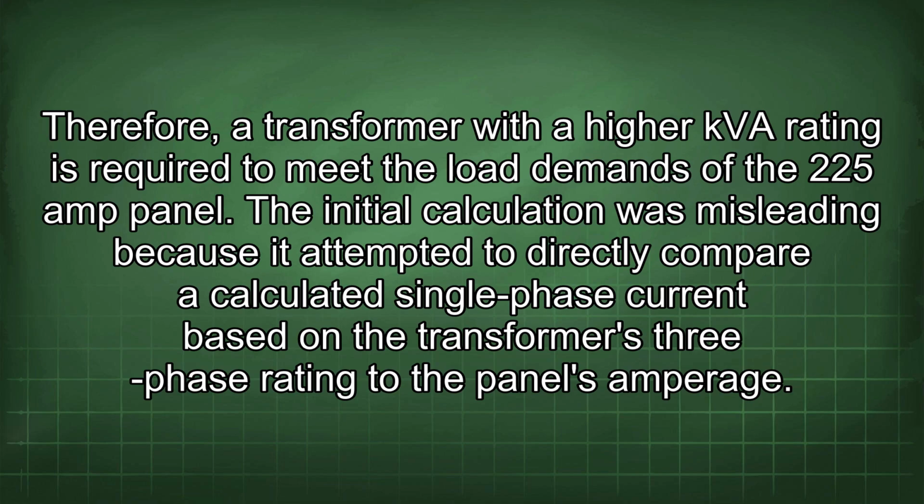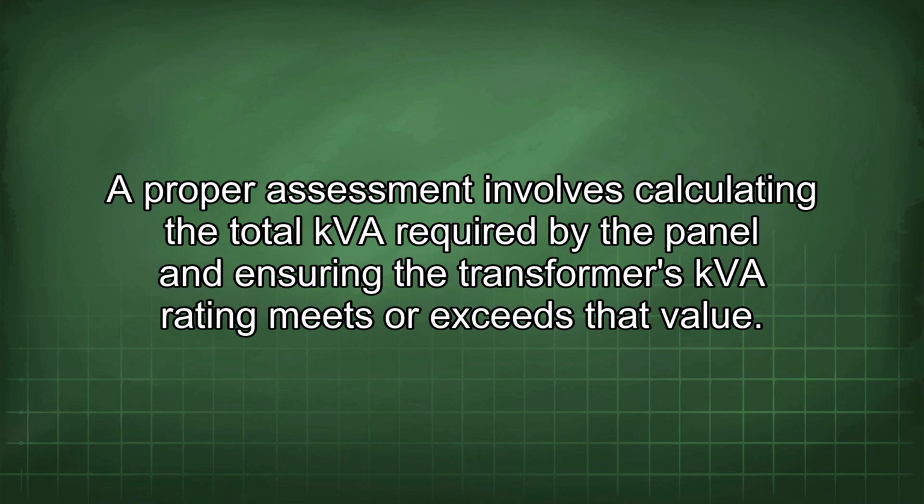The initial calculation was misleading because it attempted to directly compare calculated single-phase current based on the transformer's three-phase rating to the panel's amperage. A proper assessment involves calculating the total kVA required by the panel and ensuring the transformer's kVA rating meets or exceeds that value.